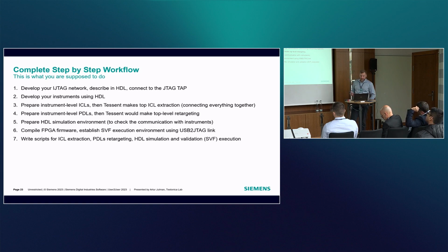Tessent would then do the top-level ICL extraction, connecting everything together, and would do PDL retargeting for the execution from the SVF executor. You also need to prepare an HDL simulation environment to check communication with instruments, and compile the FPGA firmware. That's also needed beyond the standard workflow.